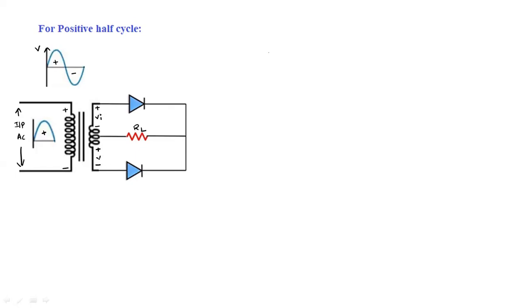Okay, it is also VI here. Input voltage is VI. It is D1 and D2, two diodes, with negative and positive terminals, and the output we will measure across this load resistance. As we are taking the load resistance at the middle of the transformer, that's why it is called a center tapped full wave rectifier.